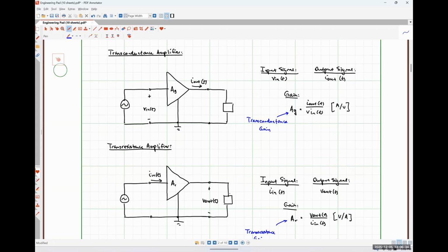So technically, yes. And we'll talk about that in a couple of minutes when we start trying to chain these things together and all of that kind of good stuff. So the goal of an amplifier is to make a signal stronger, but if we don't pay attention to some very specific things having to do with the input resistance and the output resistance of our amplifier, we can very easily accidentally make our signal weaker than we wanted to, which is literally the thing that I'm about to talk about. So great question. Yeah.